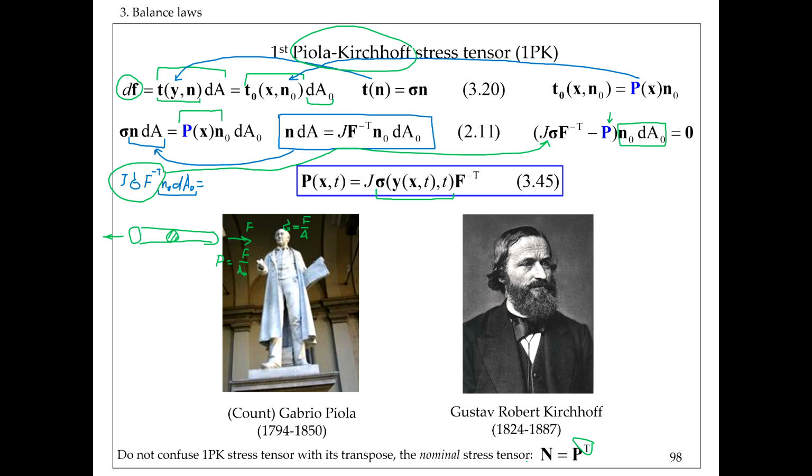So we have this new guy P, the Piola stress, as basically a source for this surface flux, right? Before that, in the Eulerian formulation, we had everything written through sigma. Now we have P, so we can entirely and fully formulate our balance law in the Lagrangian formulation. So let's go ahead and do that.